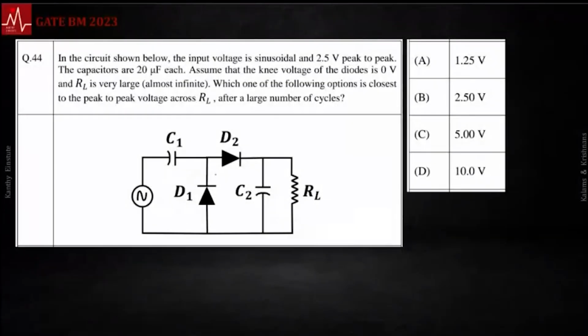Okay. So notice there is a diode circuit. This happens to be a doubler. If you want to quickly design a mosquito bat where you take the battery voltage and amplify it by a factor of 10, 100 and all that, you need to use some sort of a doubler, right? There's a voltage doubler here. Why is that? So you will be using a circuit similar to this. Why it's a doubler is very hard to explain. Whatever voltage doubler circuit is there in your mosquito bat, if 2.5 is applied, you get an output of 5. If you can recall this is a doubler, you can answer.